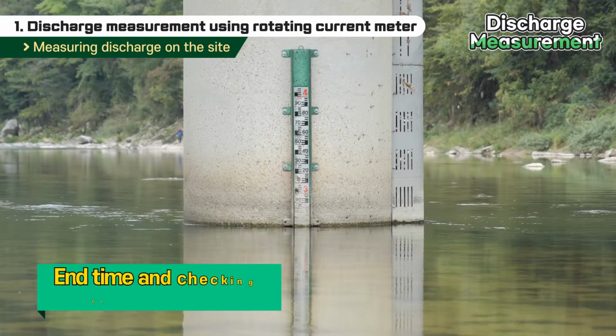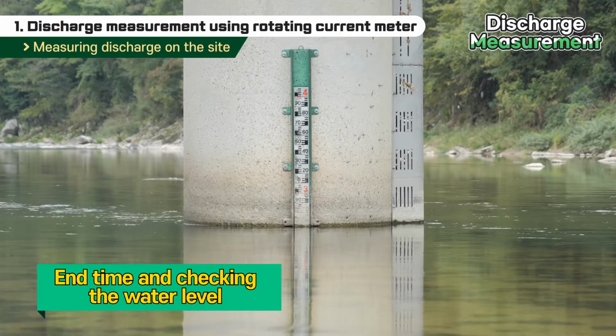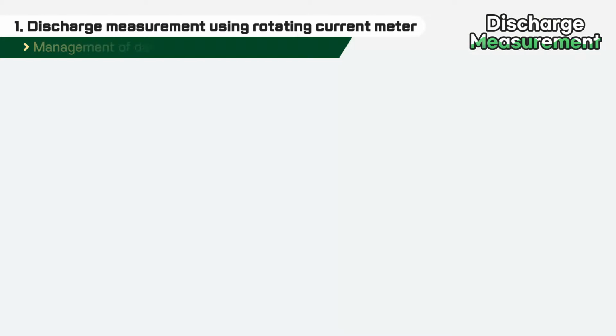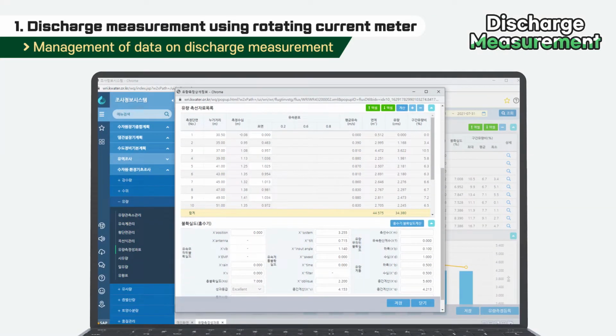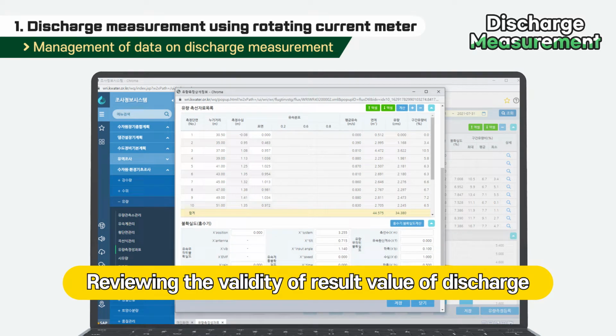When the measurement ends, the on-site worker should check and record the end time of the measurement and the water level. Once the current speed measurement is finished, discharge is calculated using an ISO standardized program or a system. The result values must be evaluated in terms of validity.